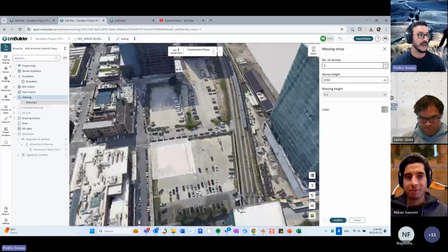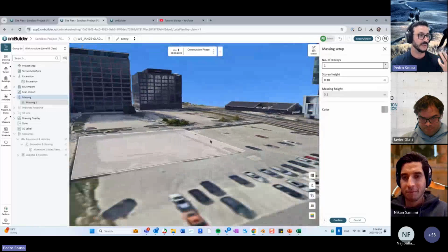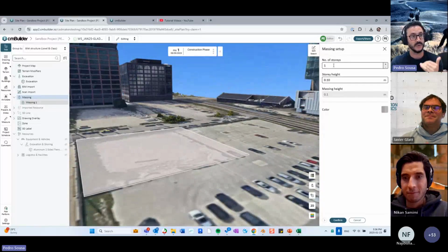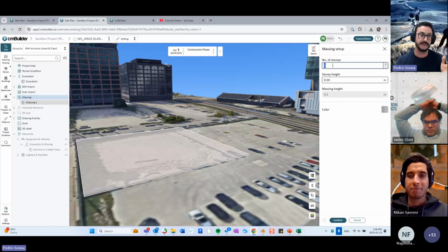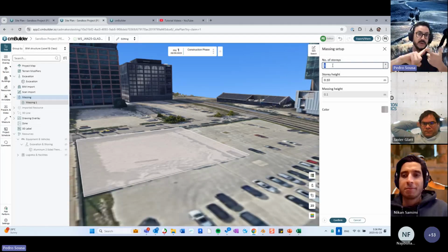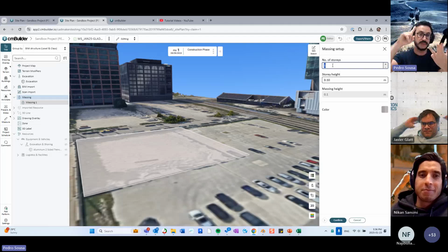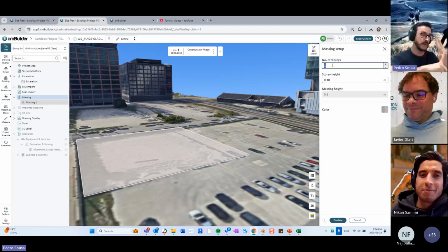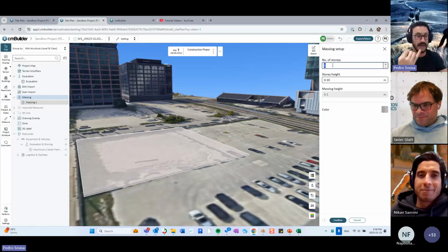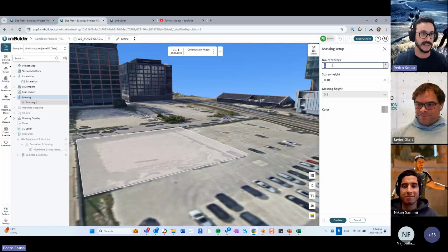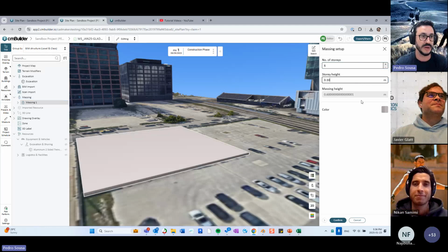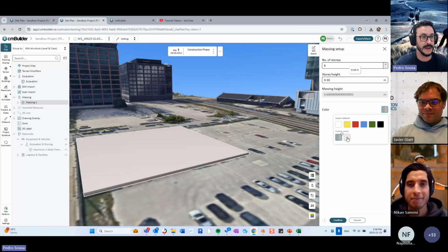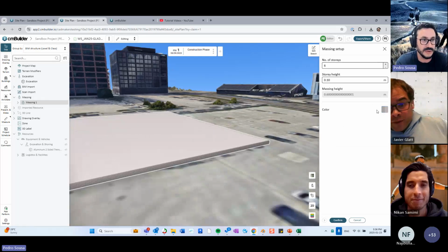And this is a workaround, okay? The idea is that you will create the stories. The number of stories will be the same as the number of stages that you have. So let's say that I'm going to do clearing, formwork, rebar, concrete pouring, curing, and then the part is done. So I'm going to create 6 stages and I'll keep a very small story height. I have the colors over here with certain transparency. You can choose if you want transparency or not.